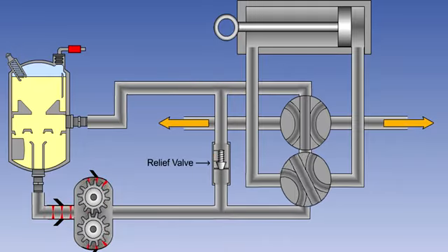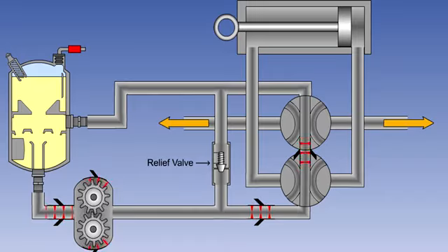The relief valve will relieve excess pressure if the selector is not returned to its neutral position. This type of system is popular in many light aircraft, which do not require a constant pressure to be maintained all the time. Only items such as landing gear and flaps will be powered for short periods of time on each flight.